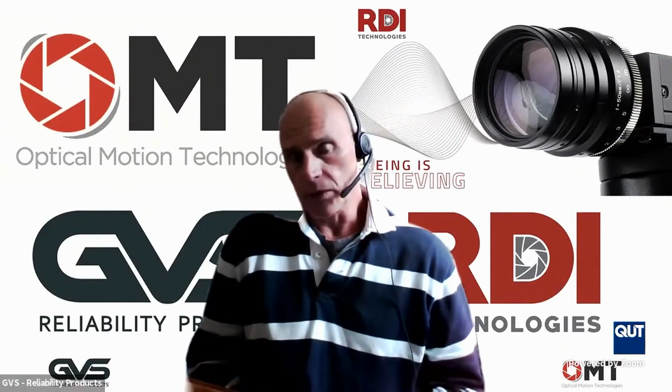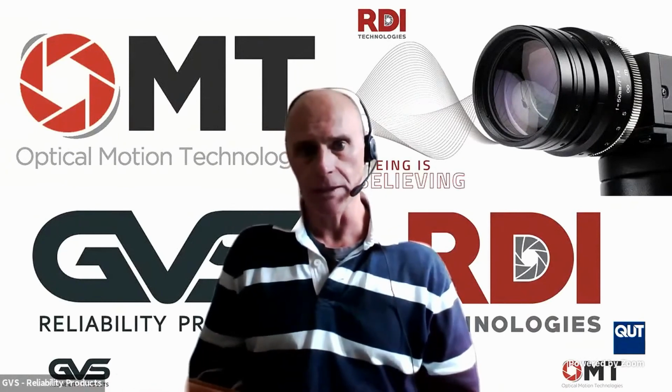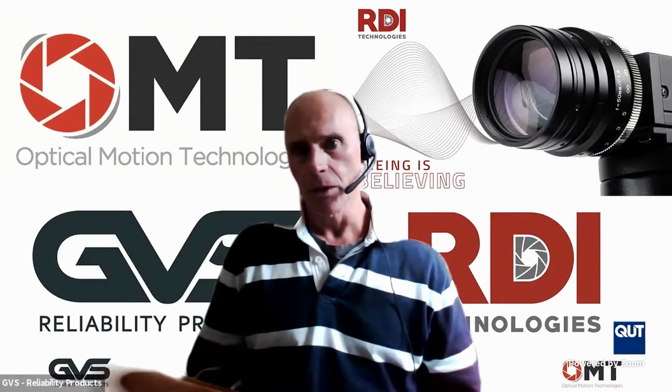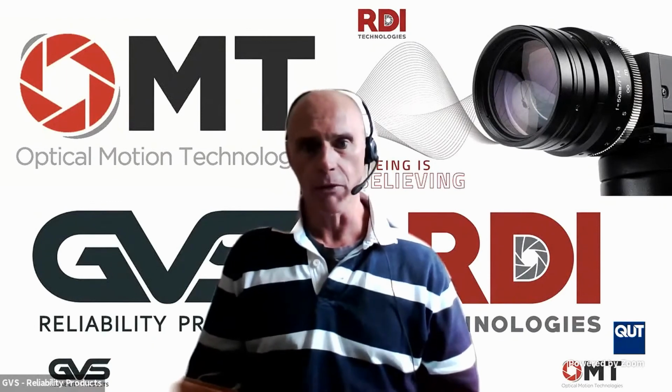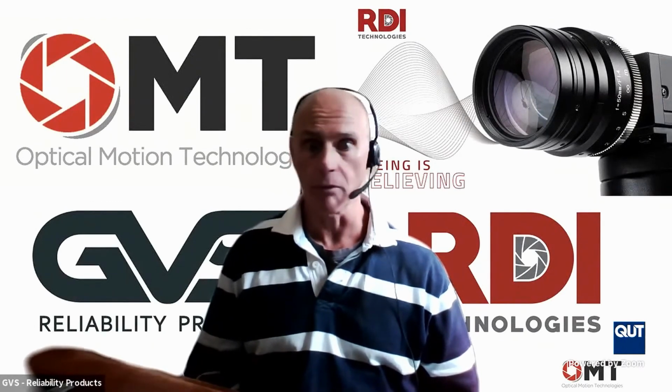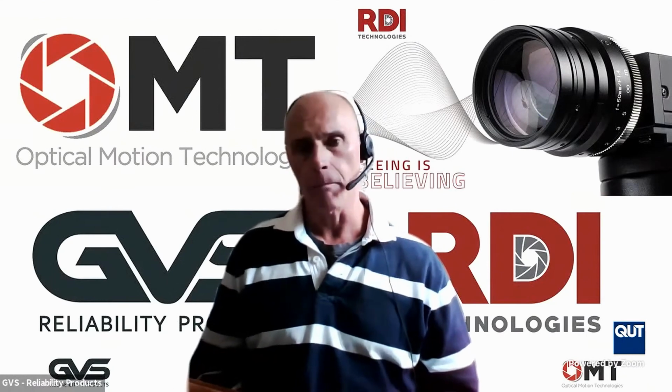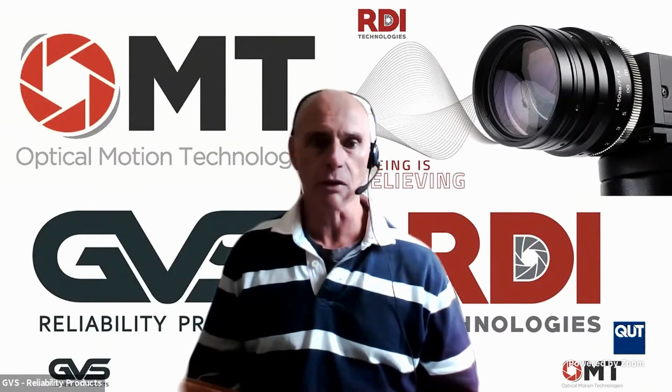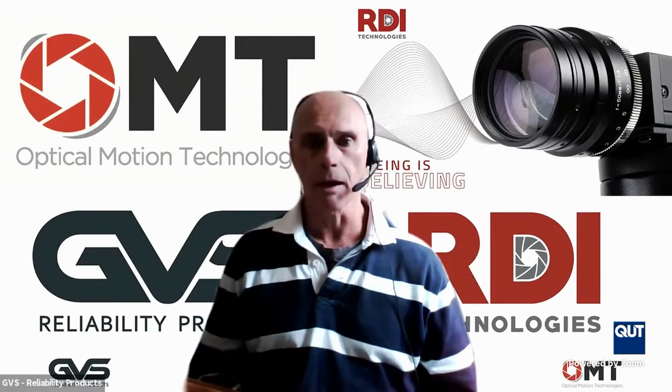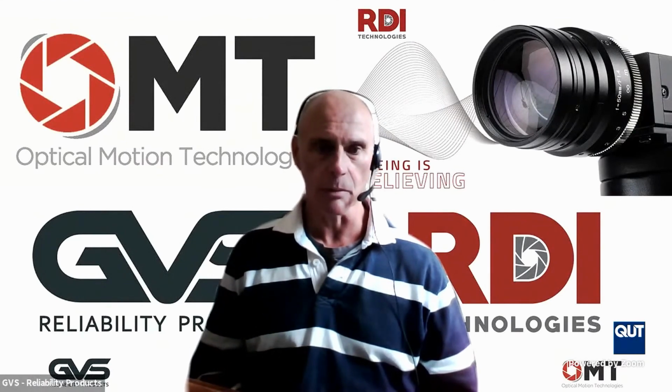But as I said, this continuous monitoring system is only new, so there would be no reason why it couldn't be set up and monitoring over a very long period of time. But again, it would be a manual extraction of data at various times during that period. That's not a major limitation, particularly around our work on trains, where you often have common trains moving over the same bridge at the same sort of times, where you can predict them, and the bridge response to a common or known load is still useful data.